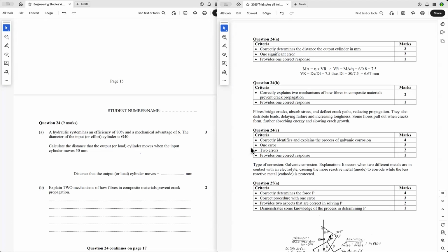Also, it hits a high tensile fiber, and the fiber will deflect the crack and stop the crack from moving. And that's basically why, if you get a crack in the gullet of a saw or in the windscreen of a car, people drill a hole at the end of it to increase the surface area, and it will stop the crack from propagating because it needs more energy to create more surfaces. And once you increase the surface area, it generally stops the crack.